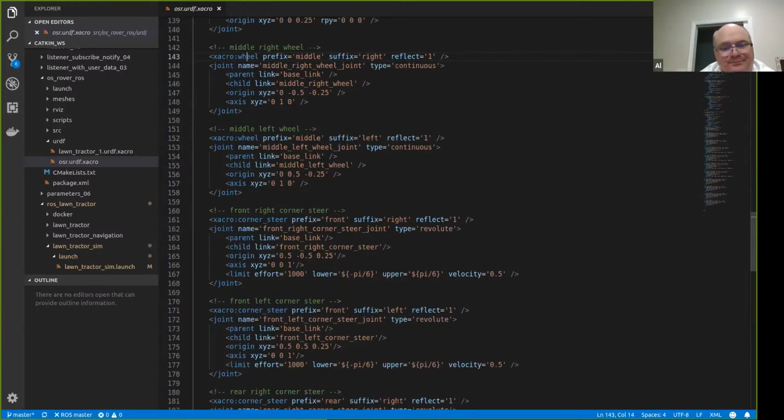Okay. Very, very powerful, actually. And that's why, remember, most of the time you see .urdf.xacro, and I was confused about why you would use both .urdf and .xacro. But this is sort of a convention. If your URDF has a xacro file, remember, the xacro is parsed to the URDF, and the URDF can be read by your RViz and also your Gazebo, right? Your RViz reads it differently, your Gazebo reads it differently.